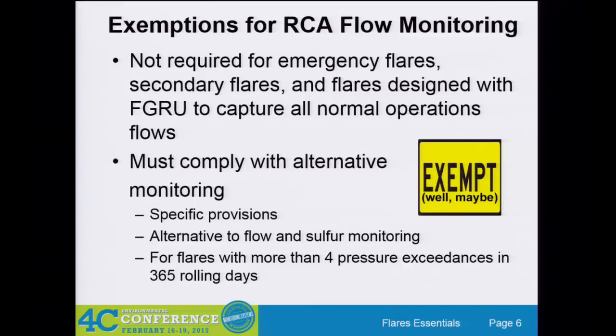So most people, even though they feel pretty comfortable with the 4, they're putting in the monitoring anyway, just because they don't want to run the risk of coming under that time crunch. Especially if they're not going to be allowed to hot tap the flare and they would have to take a shutdown. Last thing you want to do is have that day, you got to go to the plant manager and say, hey, we're taking a shutdown in the next 180 days. Sorry. That's not a conversation I'd like to have.